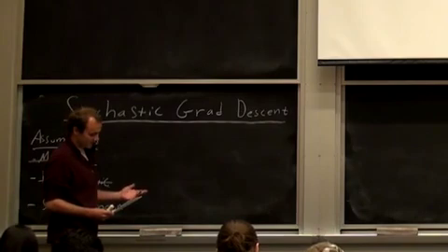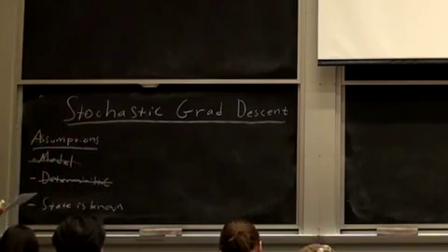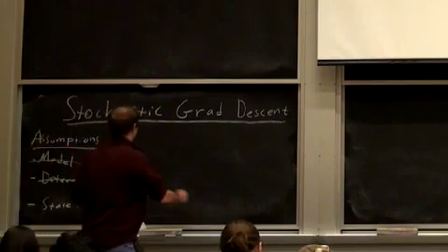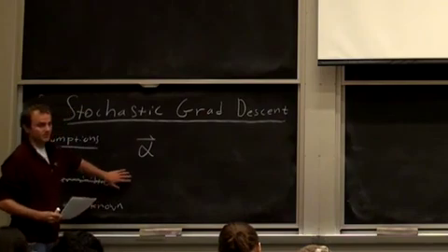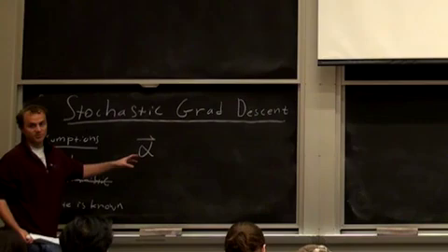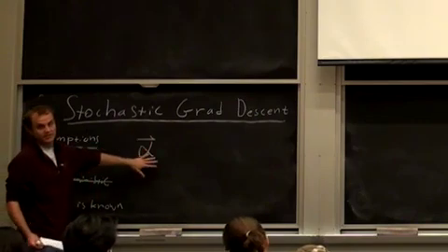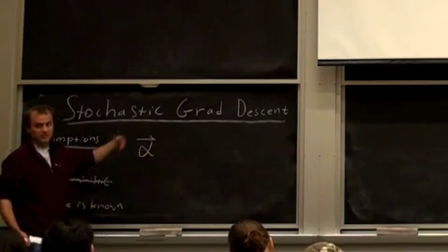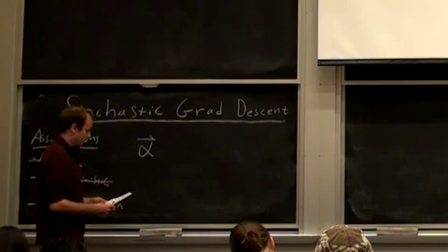So the basic idea is, again, we have this policy parameterization alpha, which somehow defines our policy. In the problem sets that you recently did, that's open loop, so you just have one alpha for every time step. You can also imagine these are gains on a feedback policy, entries of the K matrix, or PD gains, any way you want to parameterize it.